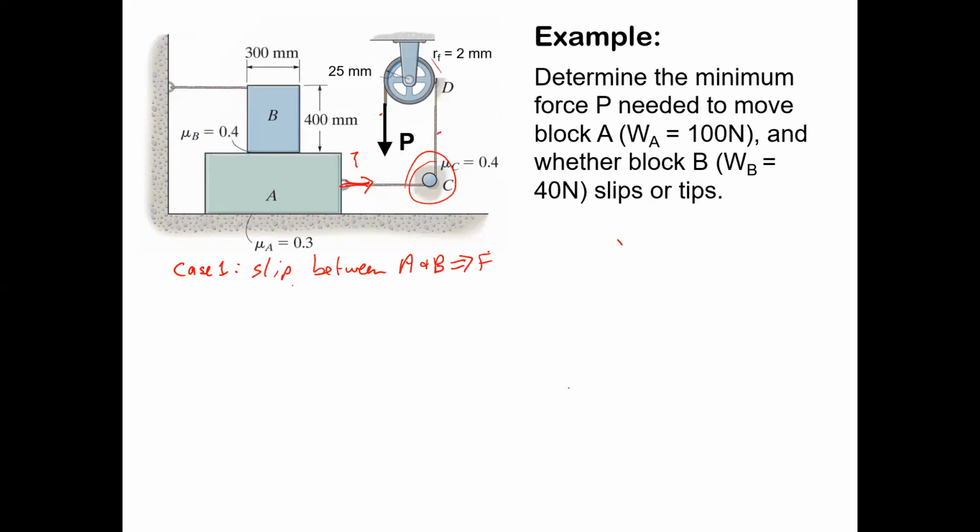So we should actually do the free body diagram. And again, I want you to remember when we're doing these free body diagrams, the bodies are separate. There's nothing touching the bodies. There's no ropes. There's nothing on them. There's just forces applied to the body. That's really important. It was missing on a lot of your free body diagrams.